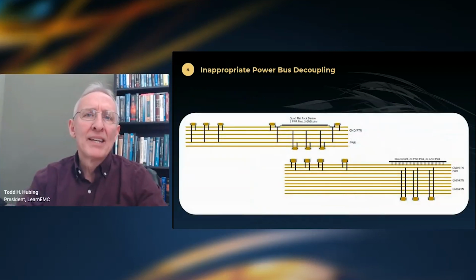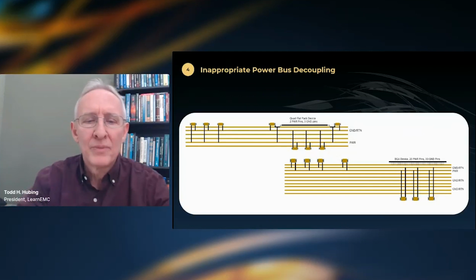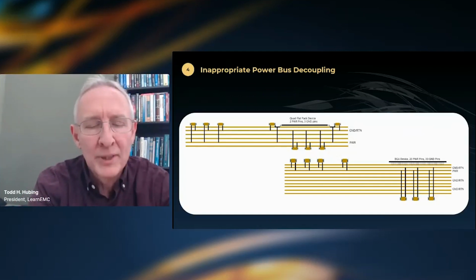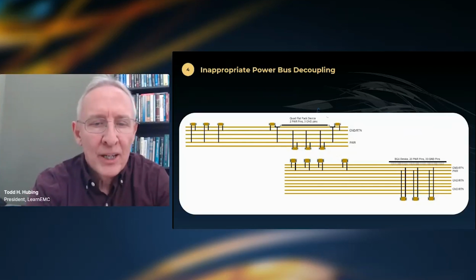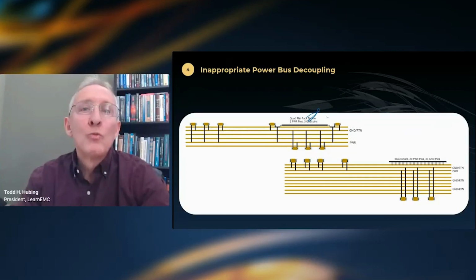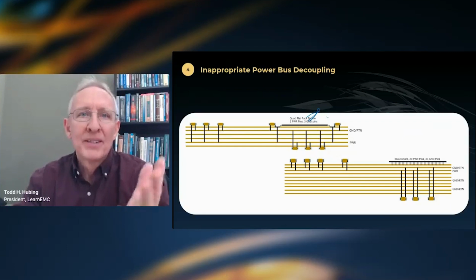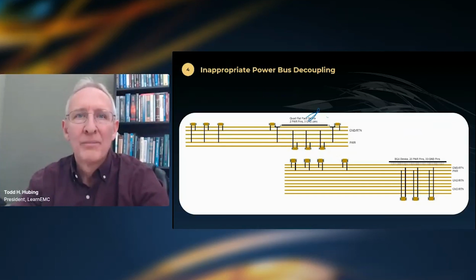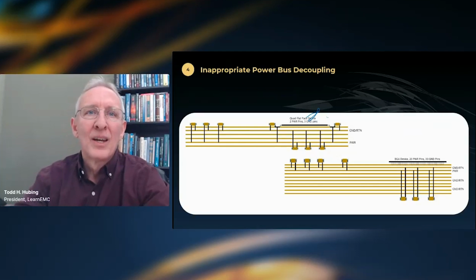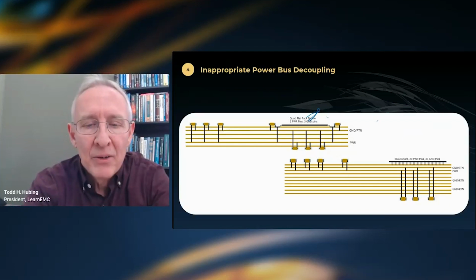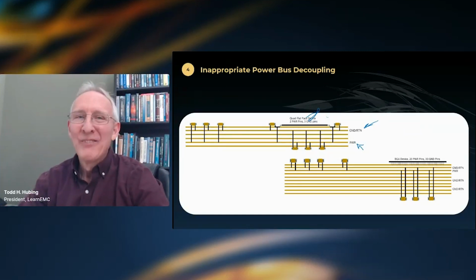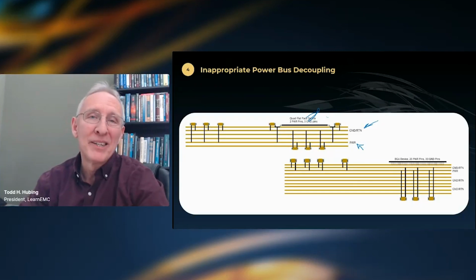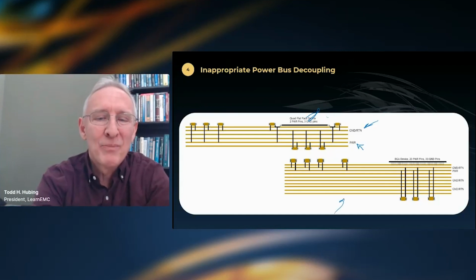But I want to talk about 2 common cases that you're likely to come into in terms of multi-layer boards anyway, with power planes. And up here, I'm showing a quad flat pack device. It has 2 power pins and 3 ground pins. So maybe it's got 50 to 100 pins total arranged in a circle. But in this case, we have a ground plane on layer 2 and a power plane on layer 5. And before you say, oh, that's a terrible stack up, this is not a terrible stack up. It would be a terrible stack up for some designs, like doing it for this board would be terrible.